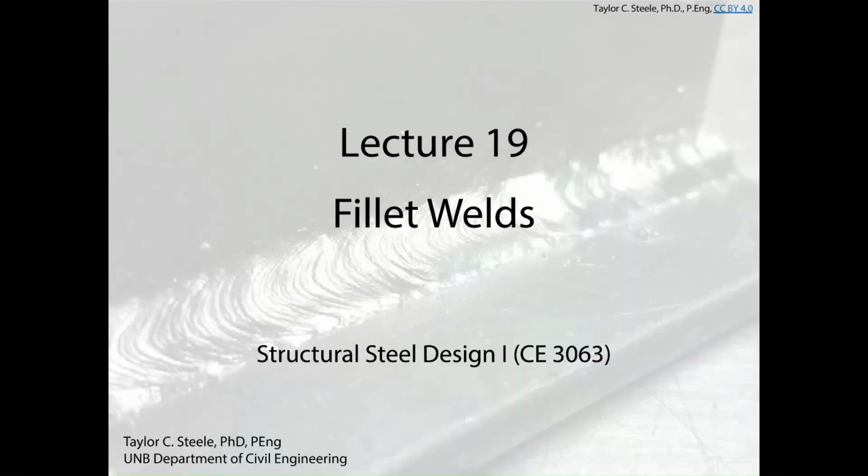at the welded connection. So last day I introduced welding in general. Today we're going to talk about fillet welds. They're the most common weld that we're going to be using, generally speaking, in structural engineering applications. As I mentioned, groove welds have their place, but 80% of welds tend to be fillet welds. They're the simplest to do, and the nice part is that their calculations are usually pretty straightforward as well.